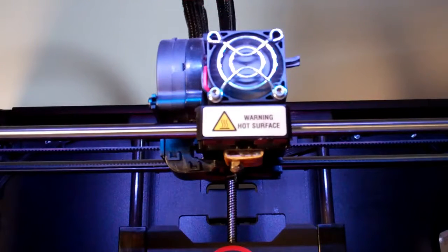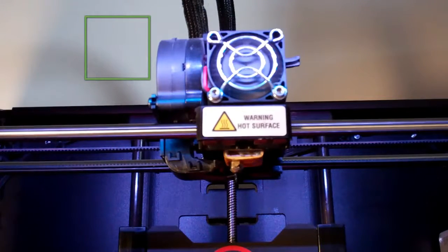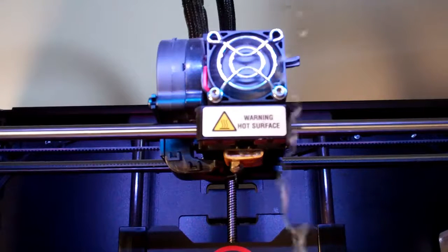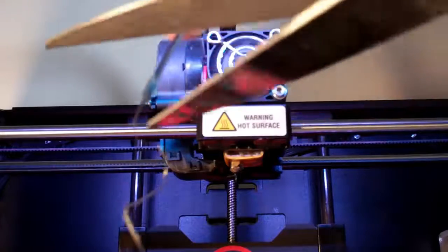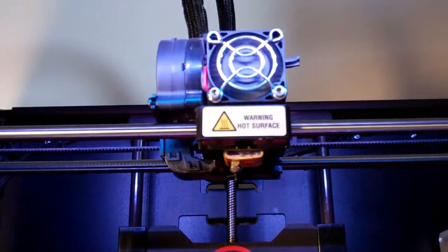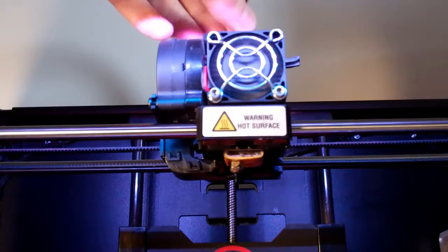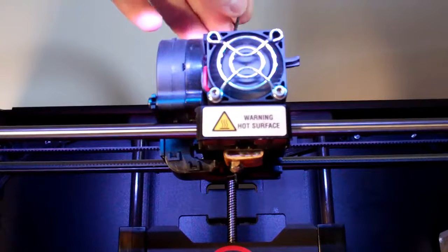In fact, as you can see there was a bit of blue PLA plastic stuck to the end of the ninjaflex there. Don't know whether you saw it a second ago. There it is, you can see it. So that's an achievement. We've pulled a bit more plastic out. Clip that off with some scissors. Reload. Same again. Push the ninjaflex in the top of the extruder.